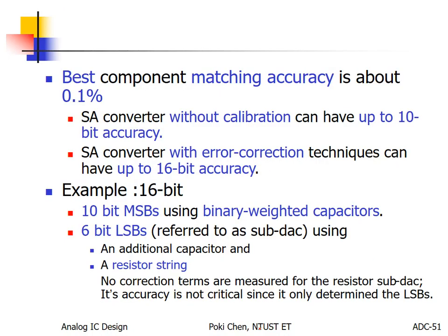For capacitor array, this is for your reference. On chip, if you do not so bad layout for them, then the matching accuracy can be 0.1%. So what does it mean? 10-bit inaccuracy. With capacitor array, without any calibration or a very complicated layout pattern, to make your ENOB better than 10 is also some mission impossible. Okay, that's it.